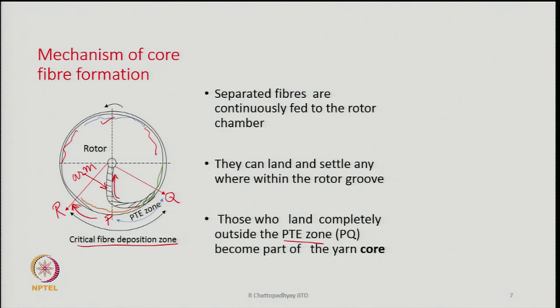However, if they lie beyond this PTE zone and also the zone PR, then they become part of the yarn core. So, if the fiber happens to lie anywhere beyond the RQ zone, then it will be part of the core of the yarn. And we will see now what happens if the fiber lands in the PQ zone or in the PR zone.